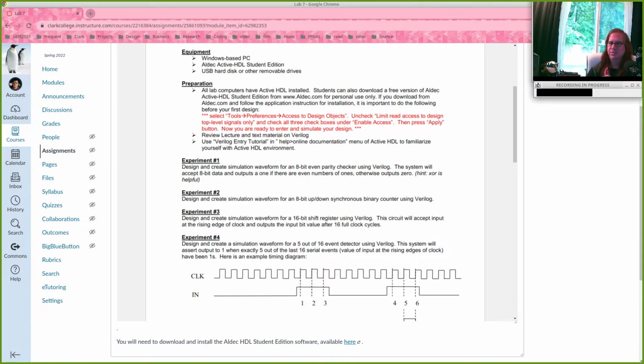So we're going to work with the simulator after break, and I'm going to show you how to write up some Verilog code, compile it, run it in the simulator, and see what the behavior is. And that's going to take the form of timing diagrams that the software will produce for us. And so for each of these experiments, you're going to have to include the Verilog code you come up with, and the simulation results. That's how you demonstrate what your code actually did.